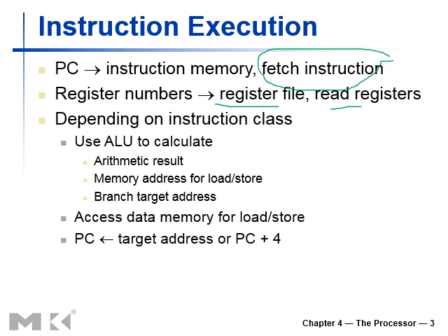Then depending upon the instruction class, as we've seen, instructions can be divided into R format, I format, and so on, depending upon the nature of the operation, the data path or the process that we're going to follow in a single cycle processor can vary. The functional units, that are the hardware components our data path comprises of, their utilization can differ depending upon the instruction.